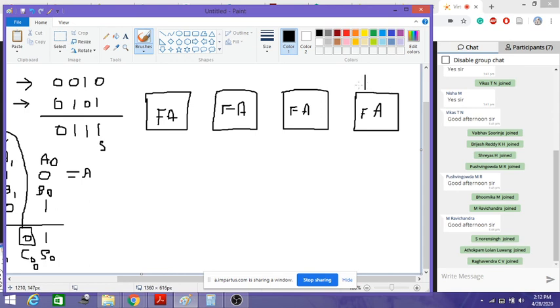Then I'll give my inputs like this. This is my A0. As I had written, in the same way I have to give the input A0 and B0. And I have one more extra input, the carry in. Let us avoid the confusion here, so I'll call this Ci0, and the first sum output I'll get is S0, and this output whatever I get here, that is my C out 0. This is connected back to the input of the next section.